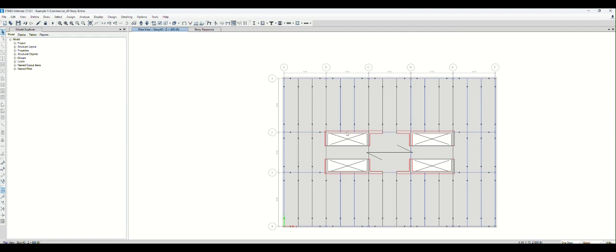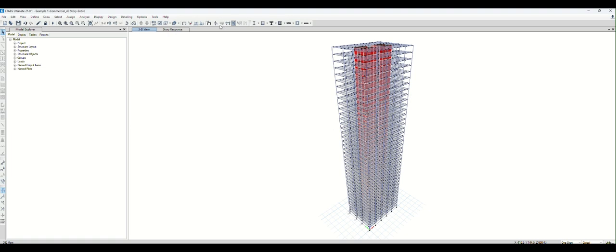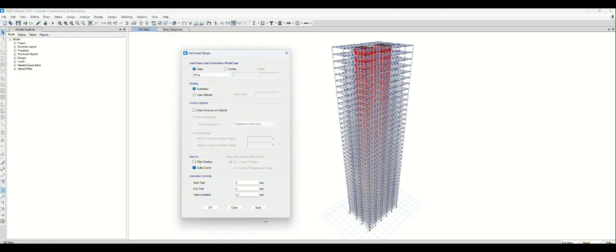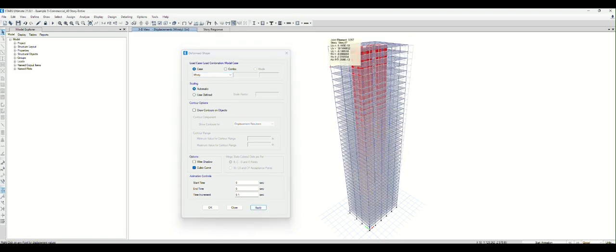Also, your core wall, the concrete tube, when blowing in Y direction, our core wall tube's weak axis shows the lateral stiffness. So that's why we end up with big deflections. You could just play around with the deformation shape. Y direction is governing. So we need to somehow size the wall, our backbone, to meet these deflections.